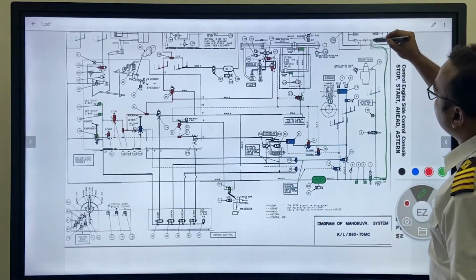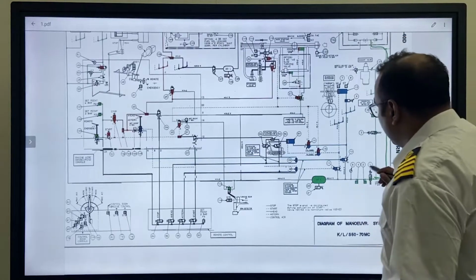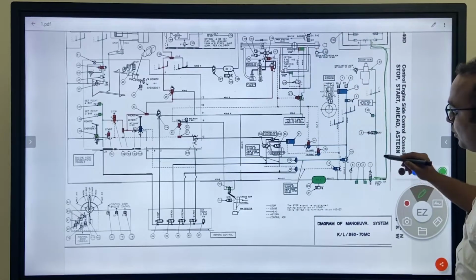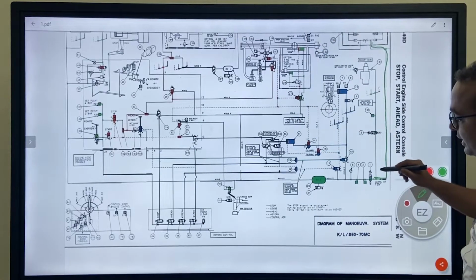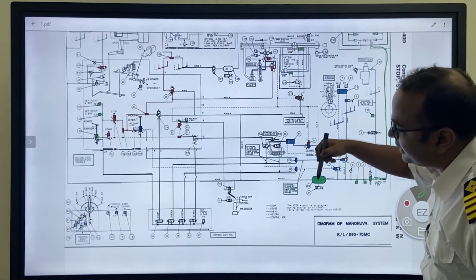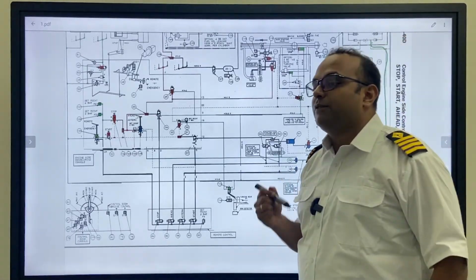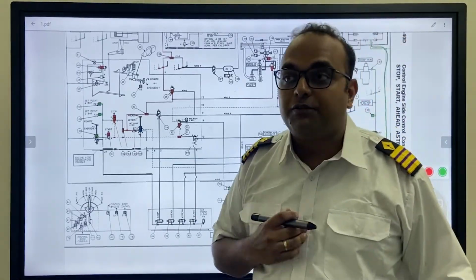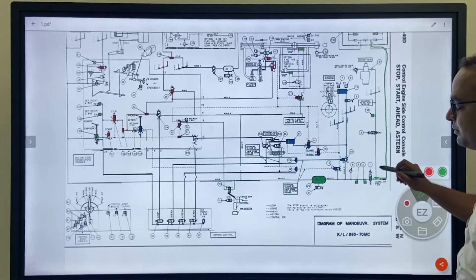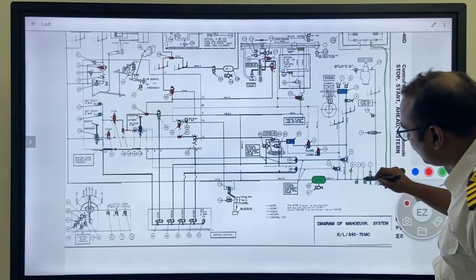So your control air has come, and what is one? One is the manual actuation of the manually actuated direction control valve, which will allow control air to go further to the right hand side. This is the same valve which you are opening before any departure. You are opening this valve, this control air line you open, and your control air goes forward.